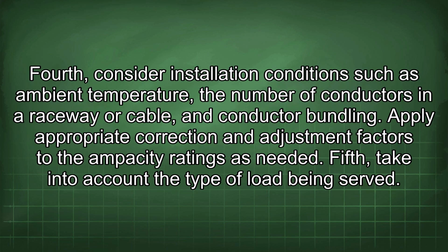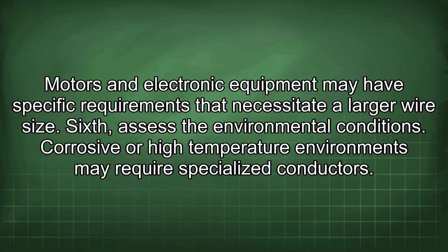Fourth, consider installation conditions such as ambient temperature, the number of conductors in a raceway or cable, and conductor bundling. Apply appropriate correction and adjustment factors to the ampacity ratings as needed. Fifth, take into account the type of load being served. Motors and electronic equipment may have specific requirements that necessitate a larger wire size.